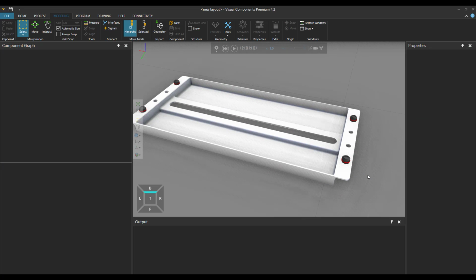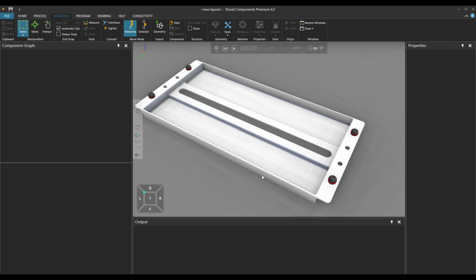You can see that those dark parts are all gone, which means that all the flipped geometries are now inverted, so we can render both sides of the faces. With this tool you can invert the geometries that have been flipped upon importing.